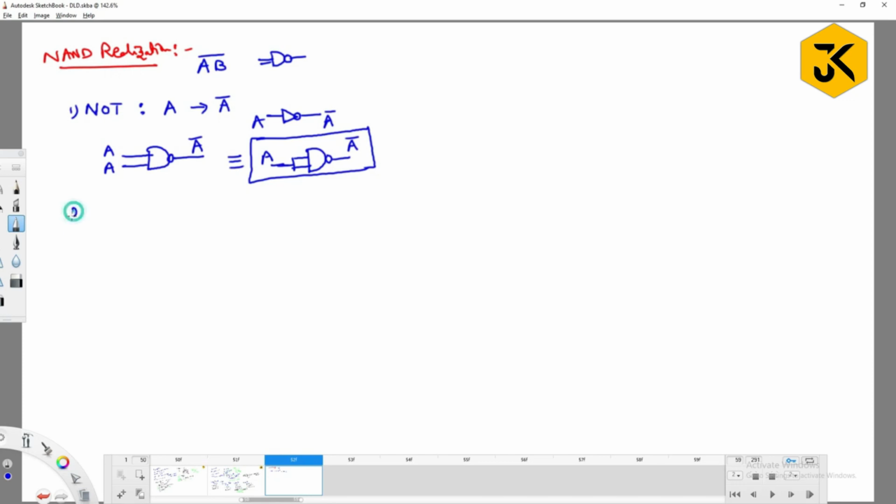Okay, fine. So if you try to take the next kind of gate, AND gate. So AND gate means what? If I am going to give A and B as input, I need to get AB. Truth table has to be satisfied, right? See, guys, for our simplicity, how can we do this in terms of NAND gates? NAND gates means what? In terms of complements, it is available. So what I will do now? I will simply perform complement over complement. So the complements cancel. Again, you are going to get the same thing, right?